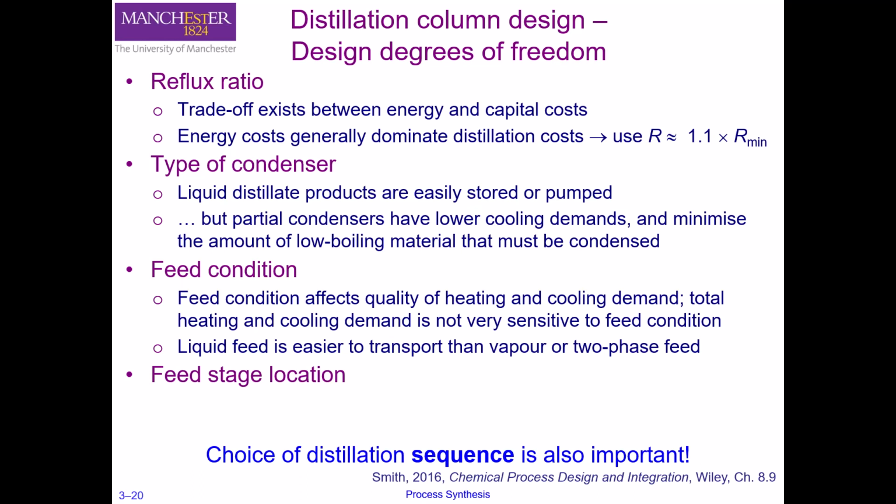In most cases, we take the feed as liquid because it is much easier to transport or handle liquids compared to vapors. But we definitely can have vapor feeds as well. As I said, just in terms of convenience, we prefer to have liquid feeds. So in your design project or in future, if you don't know what the feed condition should be, I think assuming a liquid feed should be your first choice.